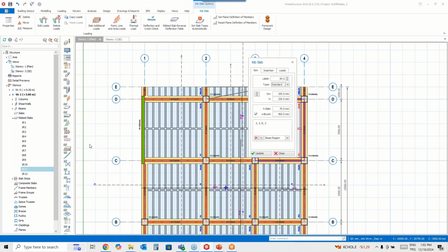I meant between the beam and the waffle slab. Mr. Abu Jabal, if you want to do this, you can use the same method as I did at the third story. You can convert them to real beam elements, delete part of the beams, and place a single slab.